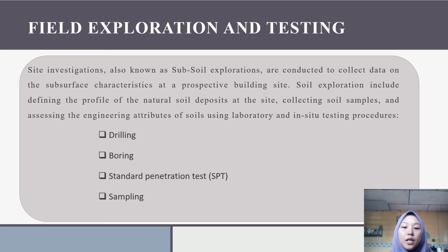For the field exploration and testing, the site investigation, also known as subsoil exploration, is conducted to collect data on subsurface characteristics at a prospective building site. Soil exploration will include defining the profile of the natural soil deposit at the site, collection of soil samples, and assessing the engineering attributes of soil using laboratory and in situ testing procedures. The first one is drilling, boring, standard penetration test, and sampling.